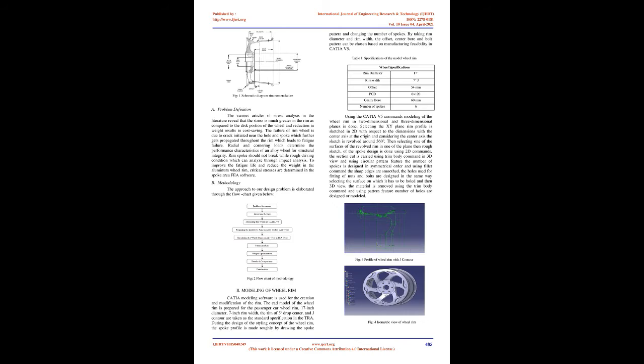Cast aluminum alloy wheels are subjected to a lot of proof tests due to their safety equipment function. The wheel has to pass three types of tests before going into production. There are mainly a 13 degrees impact test, dynamic cornering fatigue test, and rotary fatigue test [7,8,9]. Finite element analysis is carried out by simulating the functionality test conditions to analyze the stress distribution of the alloy wheels [10]. In addition, a wheel's overturning moment, lateral stability of the vehicle [11], mechanical quality, and corrosion performance must be validated by accelerated or natural corrosion tests.